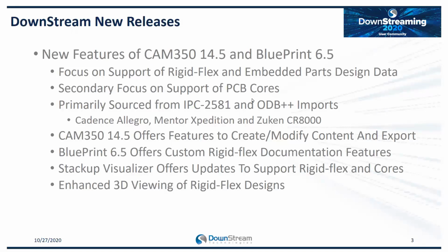Our secondary focus is on support of PCB cores. So if you're doing designs and you're doing some complex stack-up work, the support of cores to us means that we're going to take that core data from the 2581 and ODB++. We're going to show it in the Stackup Visualizer, and we're going to allow you to document it in Blueprint as a core. So we'll see that as I get towards the latter part of the presentation.